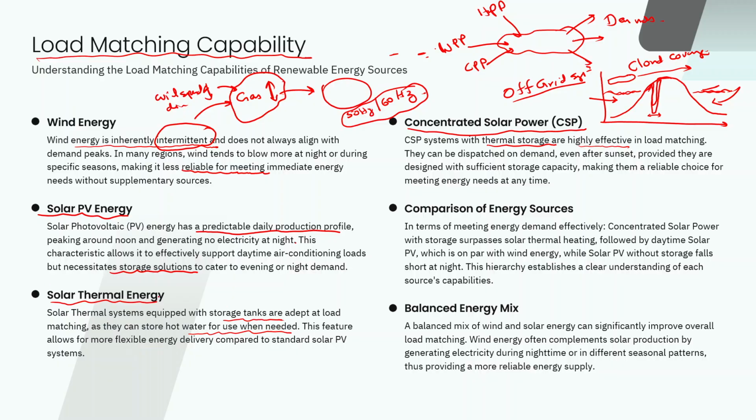Because that technology has been developed, we can easily use it rather than storing the electrical energy in the batteries and things like that, which is more costly. You can store the thermal energy or the heated water, so in the thermal storage. That will be less costly and highly effective. And when you have the thermal storage, it can be dispatched on demand, so even after the sunset, it can match the load without any issue. Okay?